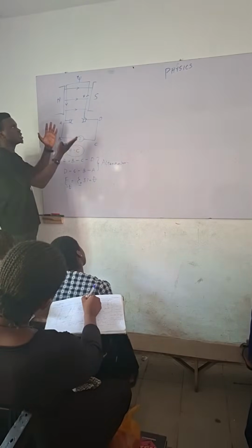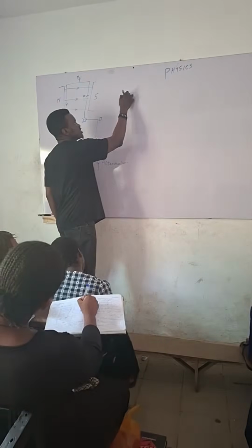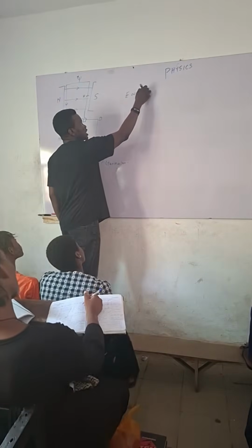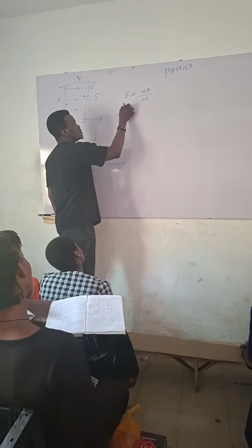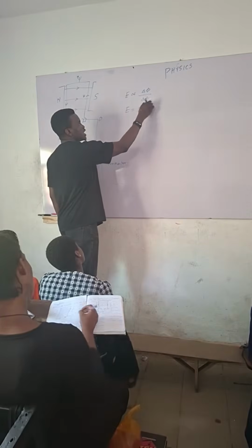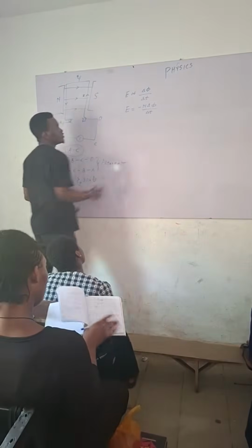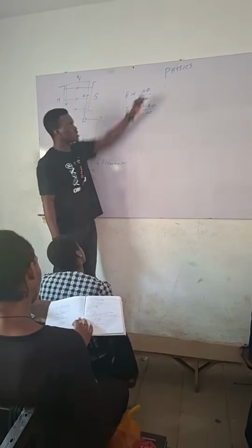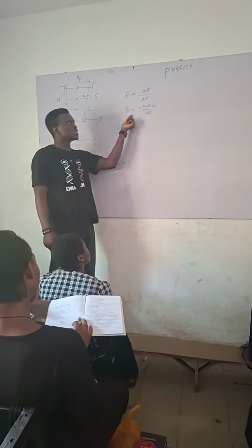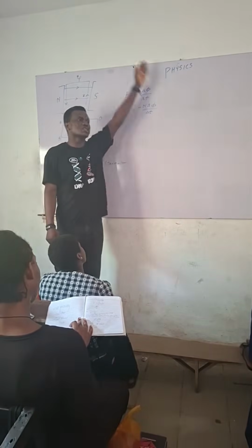But because this thing keeps flipping, and we said that the EMF generated is directly proportional to the change in flux, Abby? And from there we said that E is equal to minus N dΦ/dt. Now, change in flux is directly proportional to E, meaning that as flux is changing, E is also changing. So there's a time that E will be maximum because the flux was maximum.